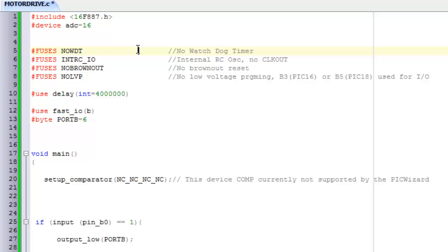So there are some functions that you have to learn by memory. You have to write them exactly how they are, either in capital case or lower case, because it's case sensitive. Now we have the number include, this is a function, so we're including this MCU. And we're saying that this device is 16 bits, okay?